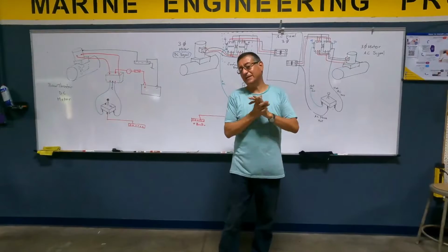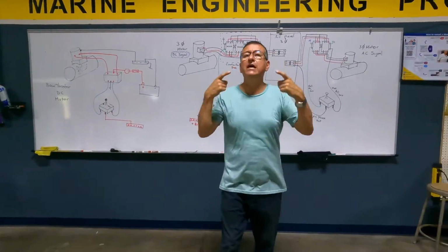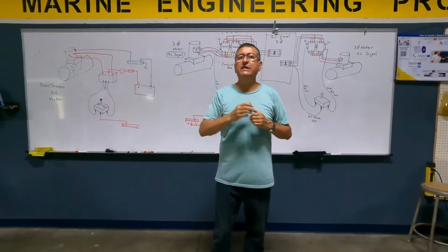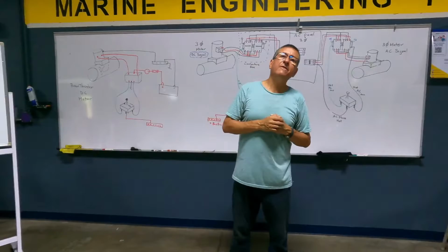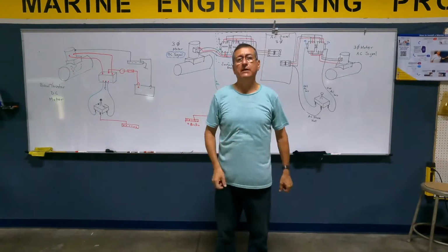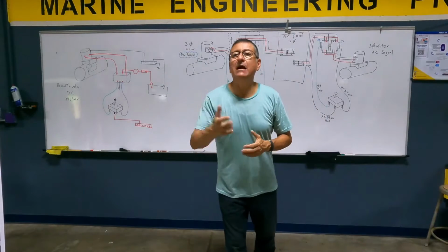In that case, pay attention. I have this situation. I have a bow thruster with an AC motor, three-phase motor, reversible motor. And the captain said, hey, my friend, I only have movement port side, no starboard side. What is the process for that troubleshooting?